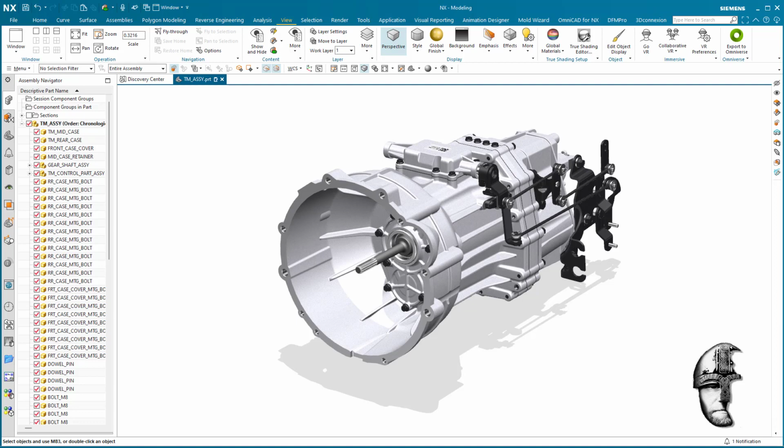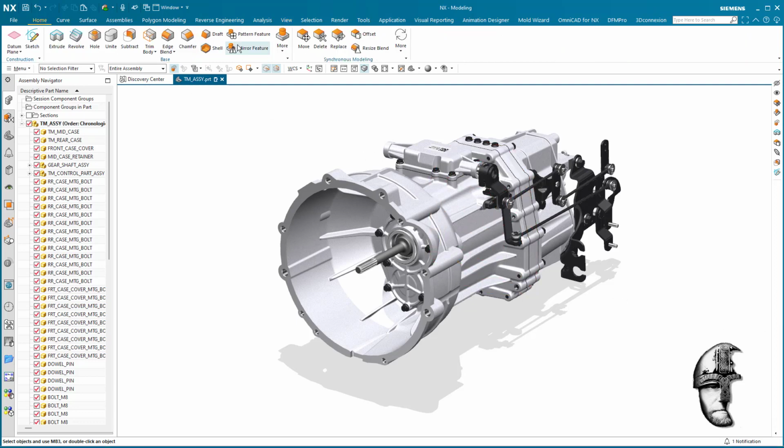One would be assembly cut, and assembly cut will work. You could use suppressed by expression to display or not display the section. It depends on what you're going to use the gearbox for downstream as well, meaning that once you're done with your work, you would suppress the assembly cut. Well, anyway. If we have a look at the assembly cut, we will need some material in the assembly part